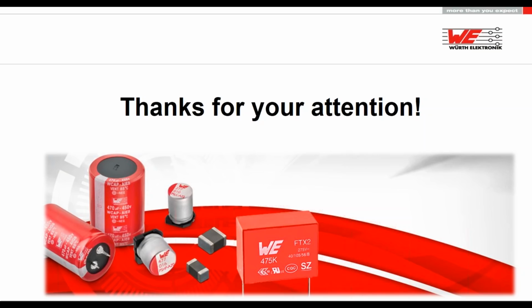So we got asked in which direction we are pushing our development. What are the borderlines we want to change? We will introduce new products like supercapacitors within this year, but for the existing product range, voltage level, especially for ECAPs, and endurance, high temperatures, these are the topics we are driving. Also for the polymer capacitors, to go up to voltage ranges between 200 and 400 volt. 400 volt with hybrid types is something we see as the next step.